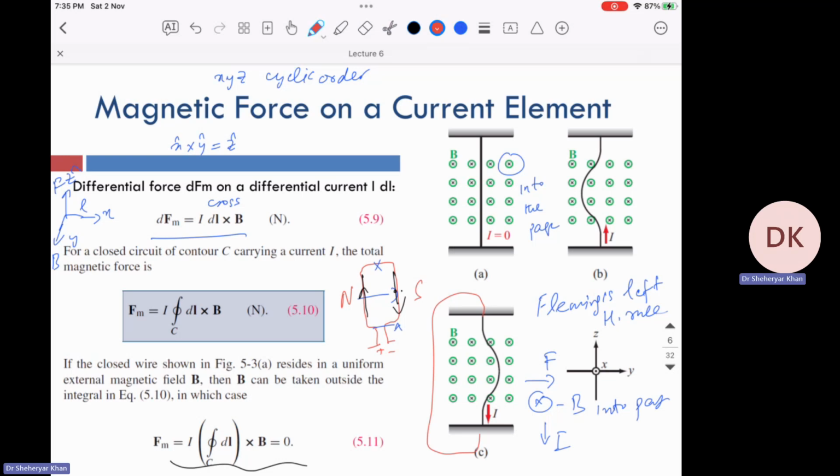if I place the conductor in a magnetic field with a closed loop and the force is zero, what does it mean? It means that instead of only this wire, if I take a wire like this also inside the field and continue one more wire here, then the forces are zero. Why? Because this wire inside the magnetic field will also experience a force. The current is going up in one and going down in the other, so both forces are opposite and they cancel each other.